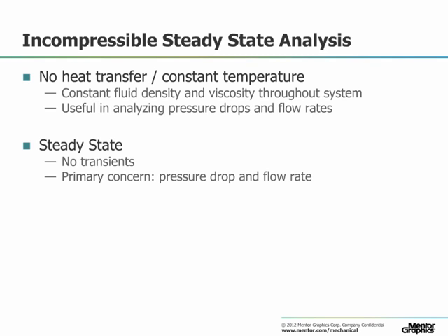When running a steady-state analysis, the primary objective is to study pressures and flow rates in the system. A constant temperature will be assumed for the fluid at all points in the system. For incompressible fluids, this also means that a constant density and viscosity is assumed in the system.